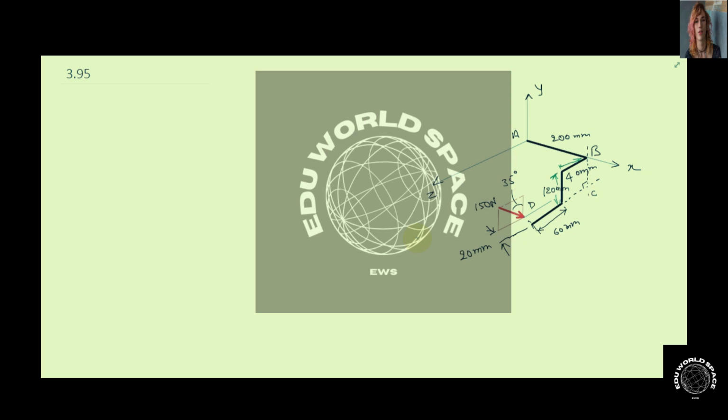So we can write this force in its component form. This 150 Newton force is going to make an angle of 35 degrees with the vertical axis. So the equivalent force will be R equals 150 cos 35 in the minus j cap direction, and plus 150 sine 35 in the negative k cap direction. It will have no x i cap component since it is in the yz plane.